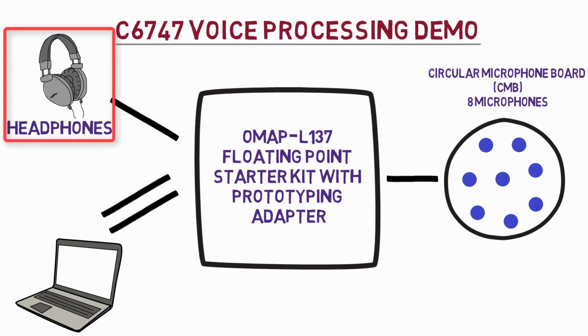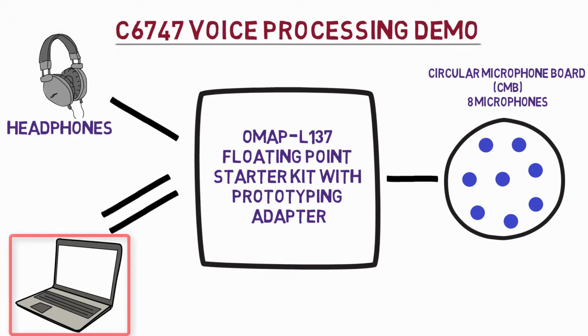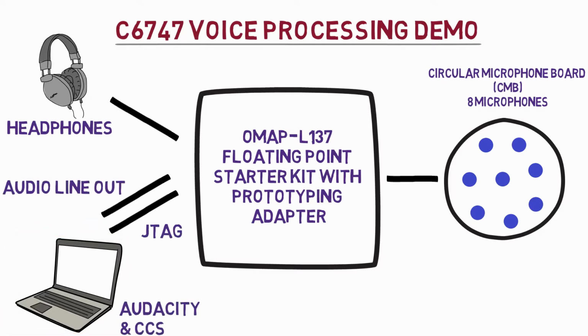The left side of the headphones will contain the processed audio and the right side the unprocessed audio. A PC running Code Composer Studio is used to control the OMAP L137 floating point starter kit in order to load the programs and for debugging purposes. Alternatively, the audio can be piped to the PC via an audio line out cable and be analyzed using software such as Audacity. The voice processing algorithms running on the C6747, which is on the OMAP L137 starter kit, are beamforming, adaptive spectral noise reduction, multi-source selection, and dynamic range compression.